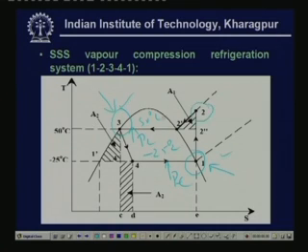And at point 2, we know the pressure is equal to the condenser pressure, and we also know that this is an isentropic process. So, S2 is equal to S1. Okay. So, we know point 2 completely, and you can find out the rest of the properties. And for point 2 double dash, you can see that it has the same temperature as the condensing temperature, that means T2 double dash is equal to 50 degrees centigrade, that is known, and we also know that S2 double dash is equal to S1. So, we know 2 properties again, and we can find out the rest of the properties.